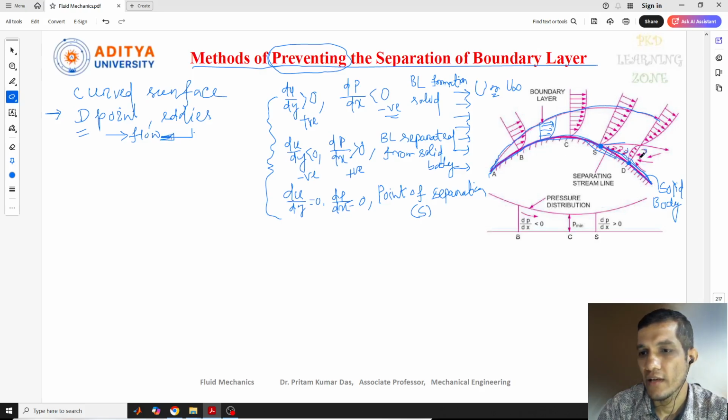So you can see inside this boundary, new boundary layer formation, what happened here at this point. The flows are in the reverse direction, and these eddies are making this. Why did this reverse direction happen? Because of these eddies which are formed here. So that will make this flow slow and it will go in the reverse direction.